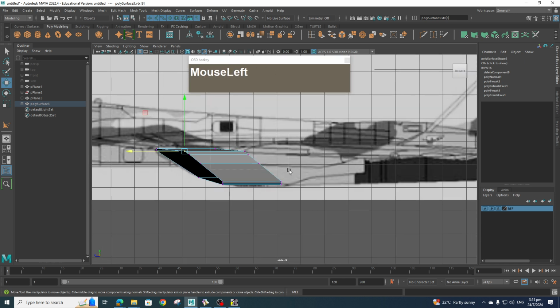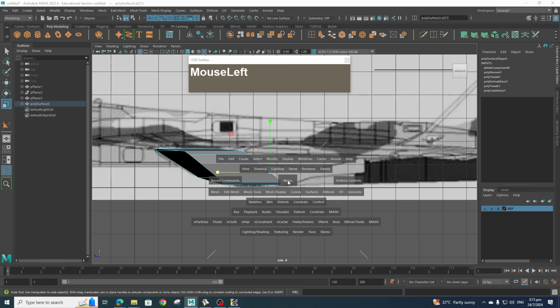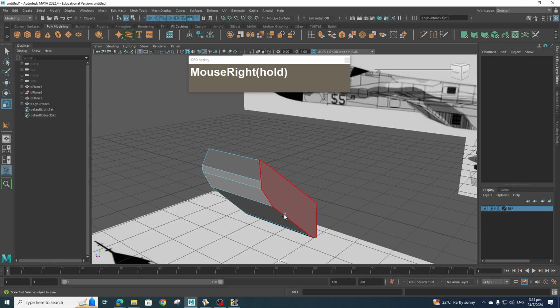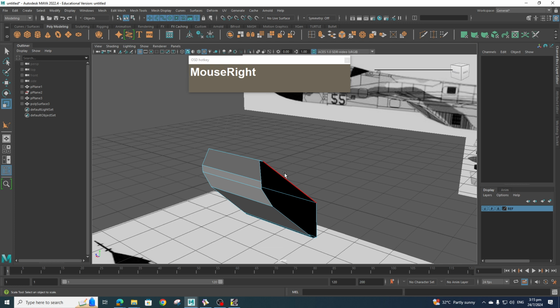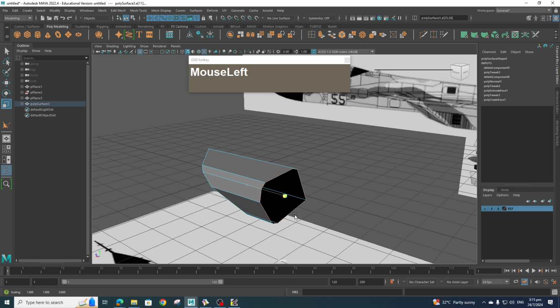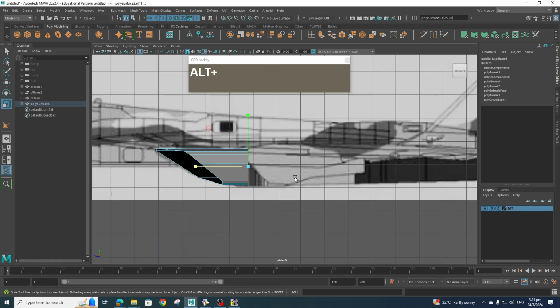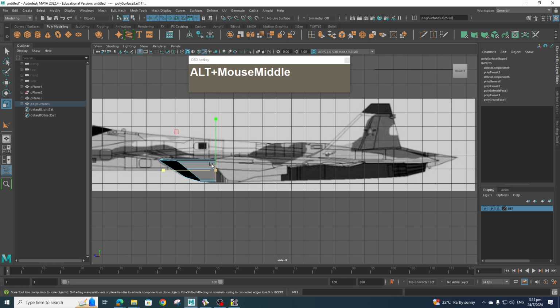Okay, so this row of vertices here, I can double click to select the open edge, and I'll use the scale tool to flatten them. Okay, actually there's another face over here, which I can delete. I don't need this face. What I wanted to do is to select here and flatten it first. Now go over to the right view. Then I can continue to pull this out until it reaches this section. This is where it starts to become a cylindrical shape, where it ends up at the jet exhaust.